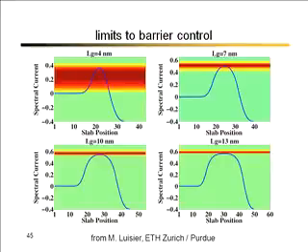So the device is supposed to be off. And the small leakage current that's flowing is flowing over the top of the barrier. That's a 13 nanometer channel length. These are some simulations done by my colleague Mathieu Luisier. In the next simulation, he made the channel length 10 nanometers. You can see that the current still flows over the top of the barrier. So we've been neglecting quantum mechanical tunneling, and our model is good at least down to 10 nanometers.